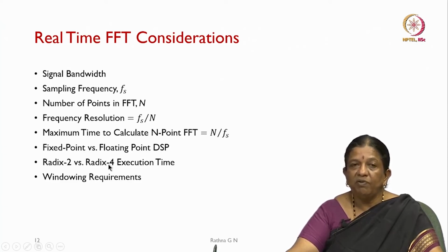So, if the input is a power of 4, it is advantageous to use radix 4, because the coefficients we have to compute in radix 4 are minus 1 or minus j. You can refer to the literature on how to do the radix 4 implementation. So, we have seen the radix 2 here, where we took the even and odd parts and then computed.